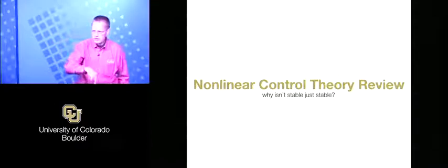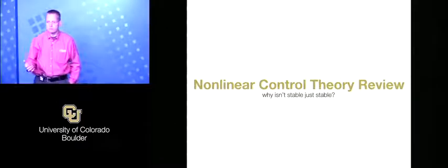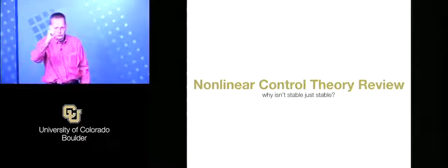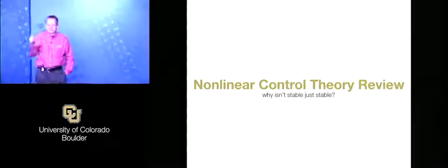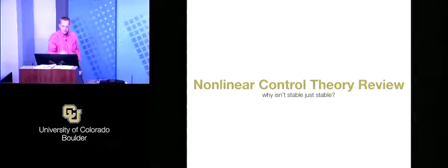Yep, imaginary axis, right? If it's unstable, where are the roots? Right-hand side. We don't want any right poles. They'll all have the poles of your characteristic equation. And if you're fuzzy on what a characteristic equation is, you definitely need to go look it up. There are different ways to get to that one. But that's for the linear system. So if it's stable, it is stable.